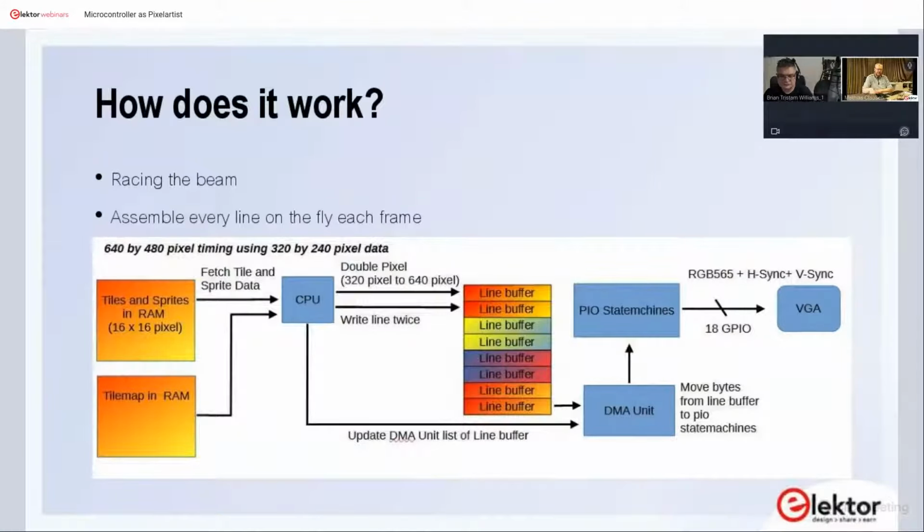And then at the point where you need to write one line of pixel data out, where the beam would run around, you will do it a little bit ahead of the beam. This comes back to what Axel Röst asked about this racing the beam you were talking about. Yes. You just generate, just ahead of the beam, the image data, compose it on the fly, line by line, and send it out. This means you have all the small little graphics around that, if composed in RAM, wouldn't fit. But then you can do multiple images or multiple sprites that form a background and put them in the right position. If they are repeating, they still look really, really nice.